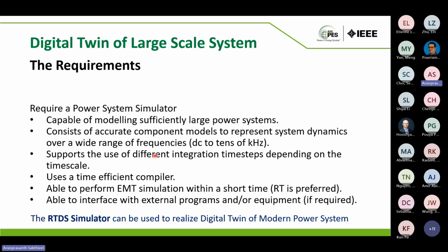So having talked about power system simulation and what we want to achieve with digital twin, it comes down to the requirements. If you want to realize a digital twin of a large scale power system, there are some requirements for the power system simulator that is going to be used to model it. The simulator should be able to model sufficiently large power systems, and it should consist of accurate component models to represent system dynamics over a wide range of frequencies. For example, DC to, let's say, 100 kilohertz or so.